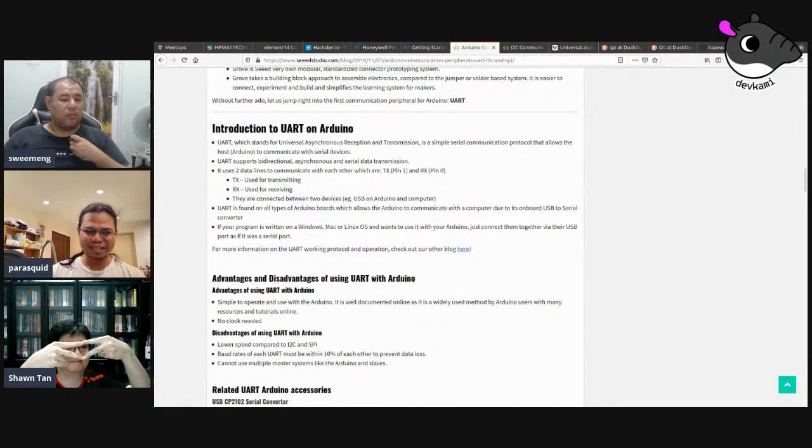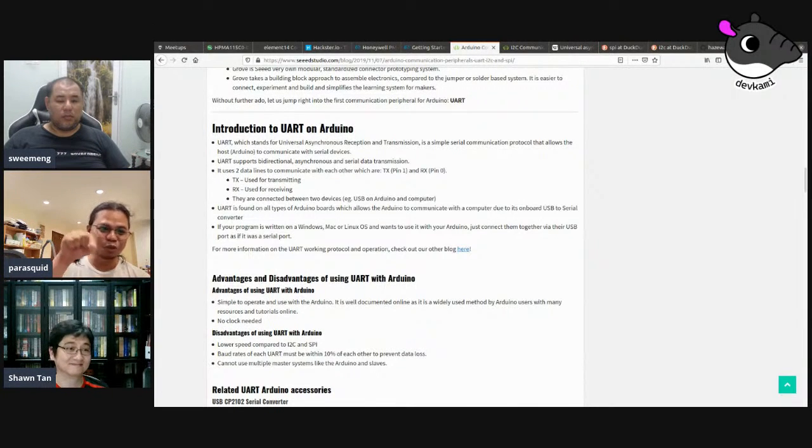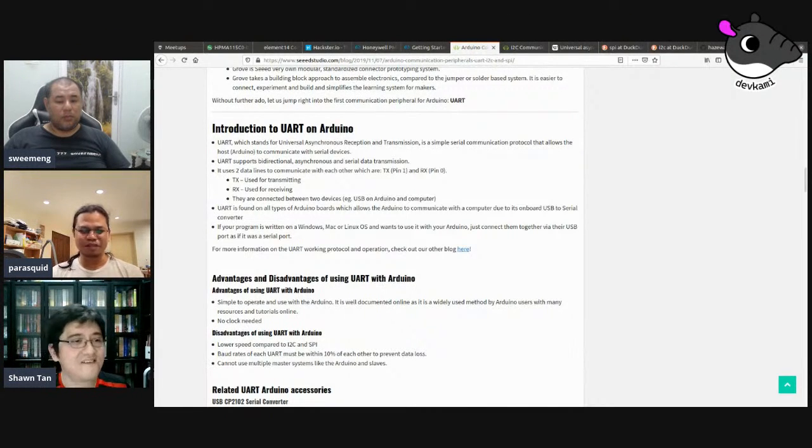Which makes that RX-TX switch really complicated, because sometimes on the PCB silk screen you'll see RX and TX, but they're trying to be helpful, saying this is where you put your TX. But why did you change it? I know what I'm doing. And so okay, that's why I'm not receiving anything, because the RX is actually a TX of that microcontroller. Always double check. But the good thing about the UART is that it's driven by the microcontrollers and it's usually a low power line. So even if you get it crossed, you won't kill anybody. Unlikely to kill anybody unless you connect it to a power line.